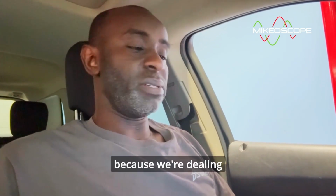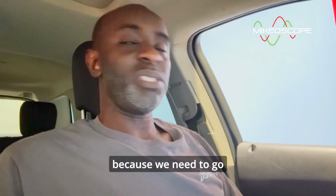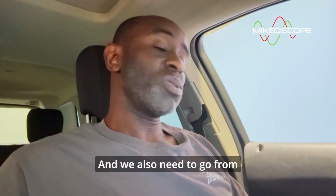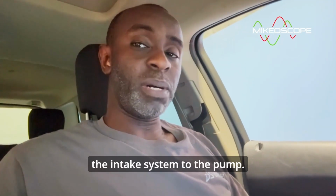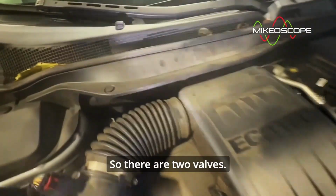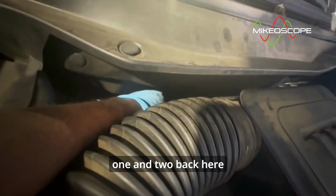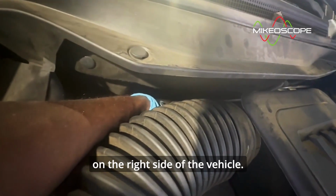Now, usually with a problem like this, I like to start with visual inspections because we're dealing with quite a good length of hoses, since we need to go from the pump to the valve, and that's pretty long, actually. We also need to go from the air intake system to the pump. So I like to start with just a visual inspection. So let's go do that. There are two valves. There's one back here that is for cylinders 1 and 2, back here on the right side of the vehicle. And there's another one. It's hard to see, but I'll show you guys later. If you can see,